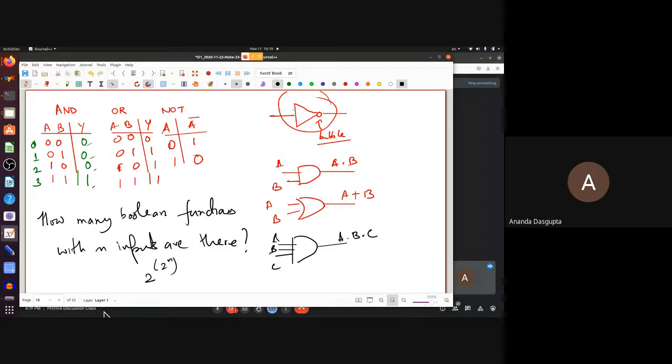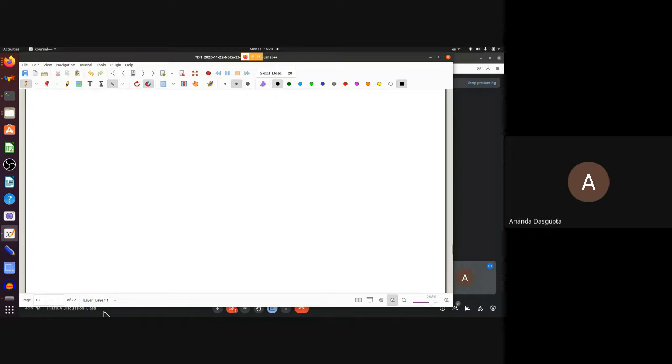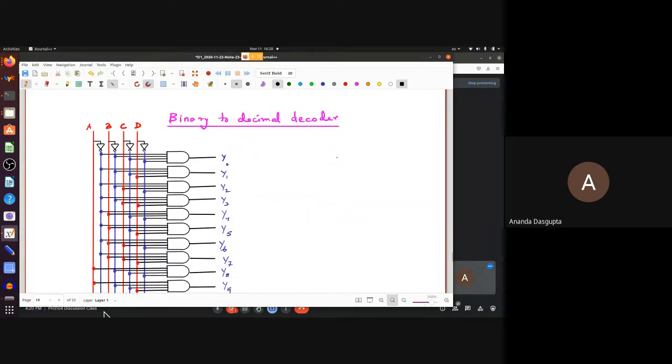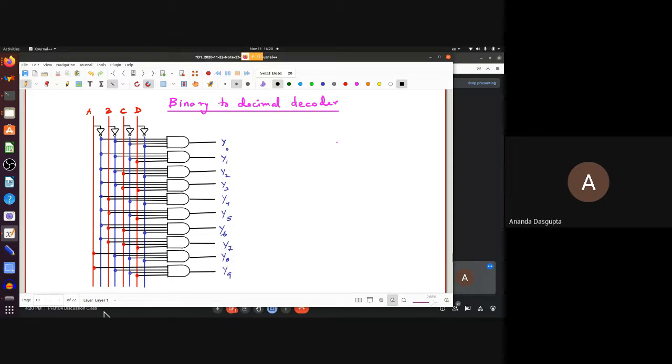So today, what I'm going to talk about are 3 very advanced circuits. The first advanced circuit, okay, I've already drawn these circuits somewhere, simply because drawing them takes a lot of time. This is called a binary to decimal decoder. This side looks pretty simple. These are all AND gates. There are actually 10 AND gates here.